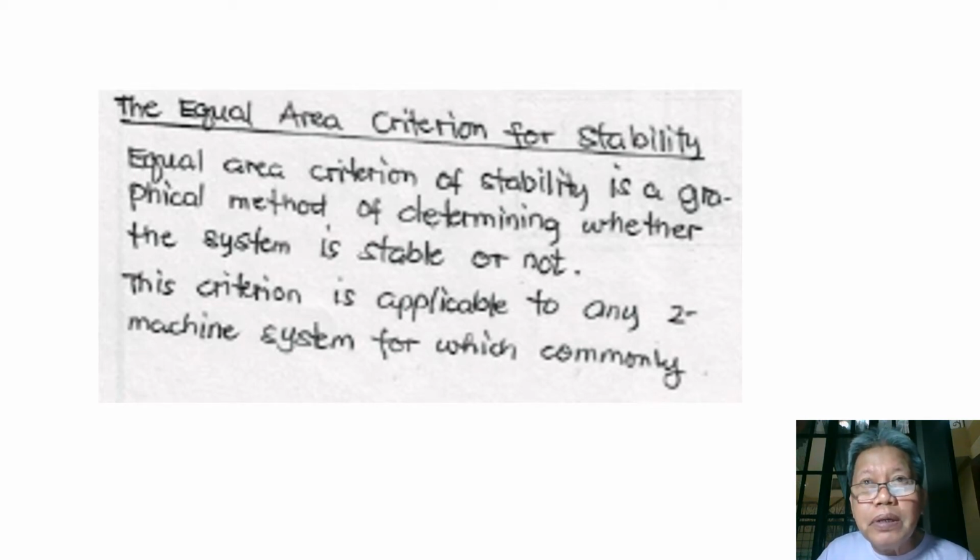In the previous lecture, we considered the analytical solution to the swing equation of the rotor angle, wherein we determined that when the roots of the characteristic equation are a complex pair, meaning when the synchronizing power is at the left side of the sine curve, where our synchronizing power is positive, then we obtain complex roots for our characteristic equation, and we say that our generator is stable.